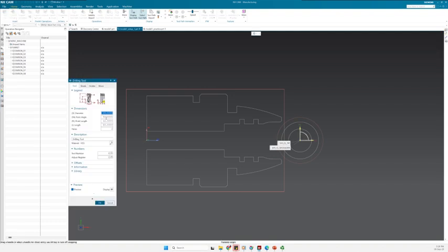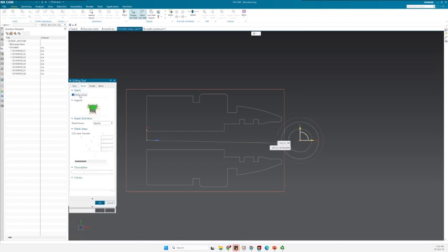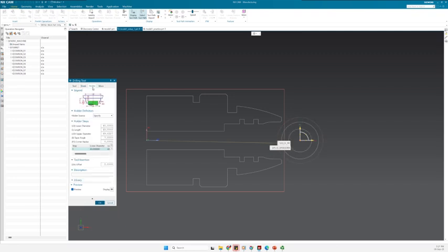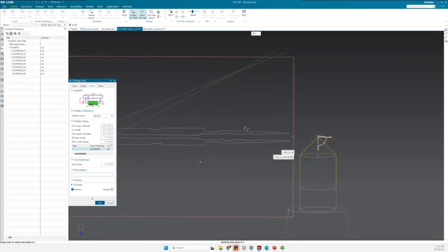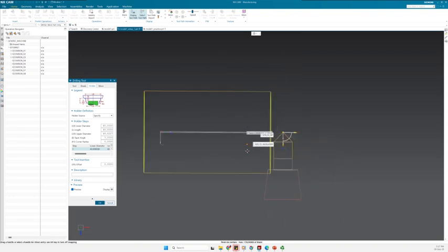Now I have the dimensions of the spot drills to be able to define it here. So what is the diameter of a spot drill, what is the length of it, what is the flute size, and then I can also define the shanks, for example, here. So these are also important parameters that you need to define as realistically as possible. So best case scenario, you should ask your workshop members or your colleagues what the available tools there are, and then define it, because these are the ones that finally define if we have any collisions or not.